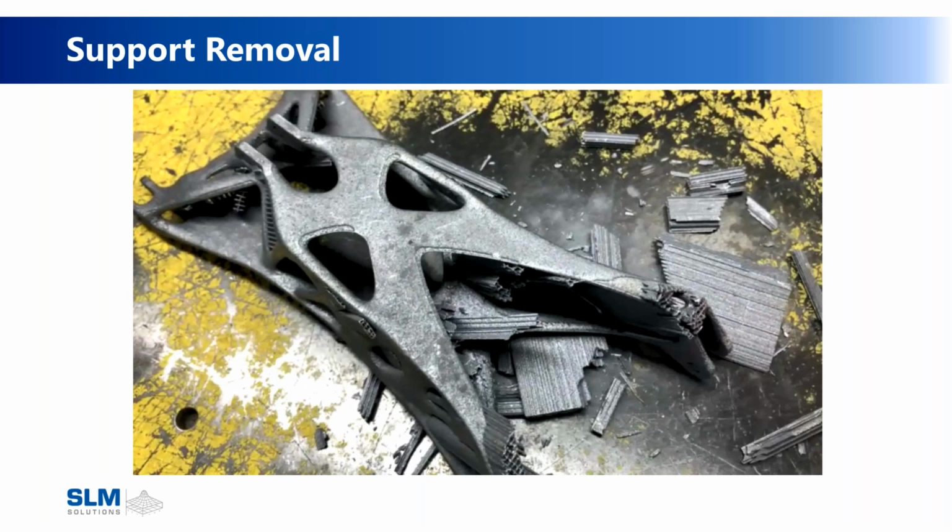And this is the same material. So once this material is printed, it has to be scrapped. It can't be reground and added back into the powder bed process. So another thing in reducing the part cost is reducing the amount of support needed, because at the end of the day, that support is just wasted material. We can't use it. So we need to limit it to a point where it makes sense, supporting this properly, but also keeping the part supported so that it finishes its print.